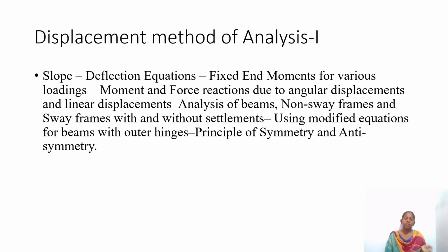video lecture. The displacement method consists of slope deflection and moment distribution. Both are displacement methods. Even the stiffness matrix method is also a kind of displacement method, where the displacements are to be calculated. The flexibility method, matrix flexibility method, is a force method where the forces are to be calculated. The forces are the unknowns. So here the displacement method is the slope deflection method, where the displacements and the rotations are the calculations. One thing I want to